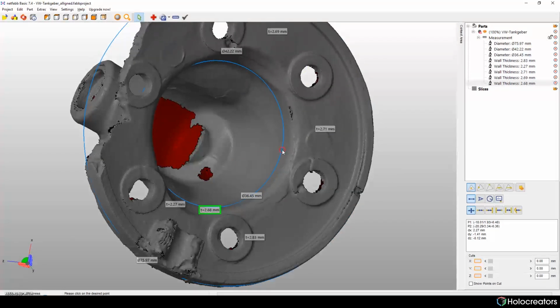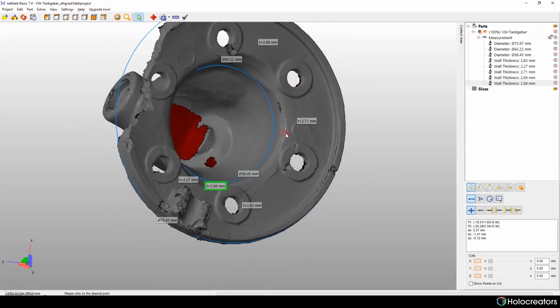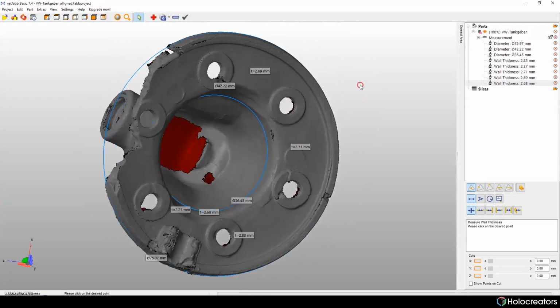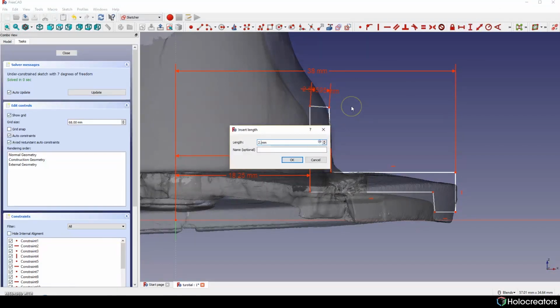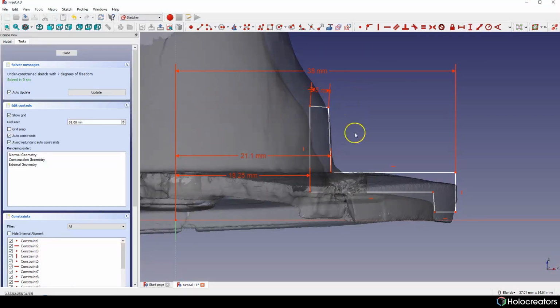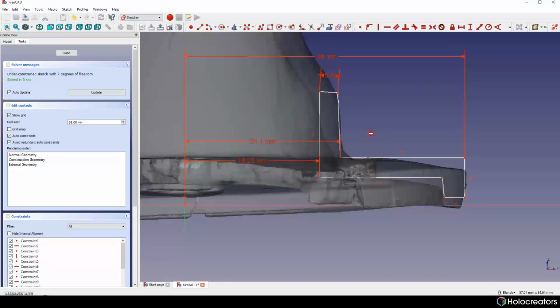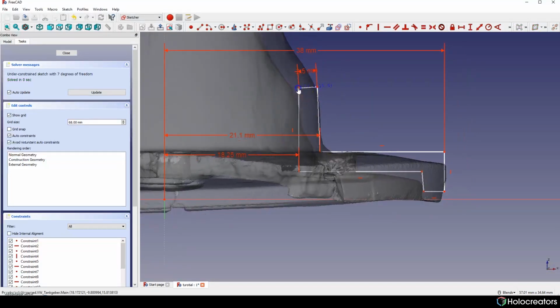I will put something average in it, and I will maybe choose 2.5, it's gonna be good. I'm just choosing these two vertices, and I will put 2.5 in it. Also, I will make these two lines perpendicular by pressing this constraint.